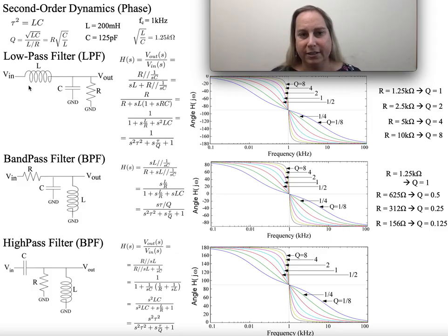One is I've got an inductor with an R and a C, and this is basically a voltage divider. You might say, why is it a voltage divider? Well, again, remember my capacitance is 1 over SC. My inductance is just S times L, and these are in the Laplace domain. It's wonderful when you get to deal with circuits in Laplace because your L's and C's can all basically just turn into resistors. You can do a whole different permutation, but we'll just start with that, okay?